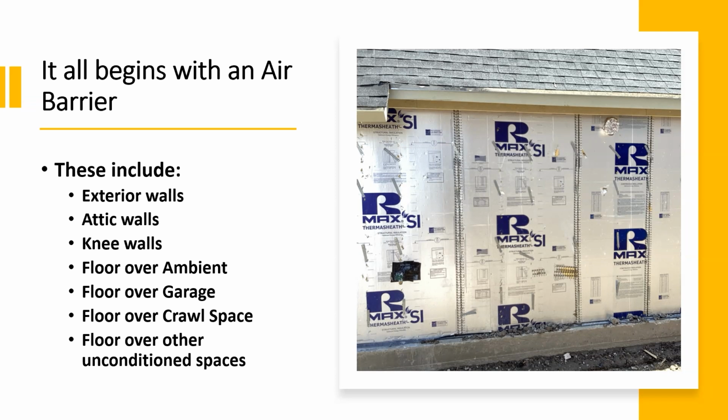So the energy verifier must identify all these locations to determine if the air sealing of the material being used is in compliance and meeting the intent of the code. That's all seams are sealed, all gaps are sealed, all penetrations are sealed, all the material is installed per the manufacturer's instructions.